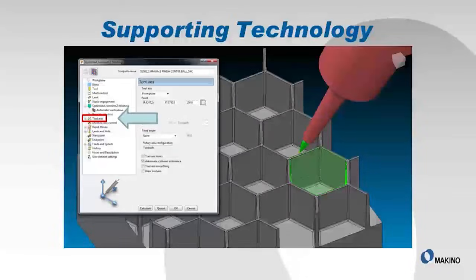You have automatic features where we can actually lead and lean the tool away based on a holder or clearance condition, helping to allow the system to automatically make that tip for you instead of using complex 5-axis geometry to support the tool axis control.